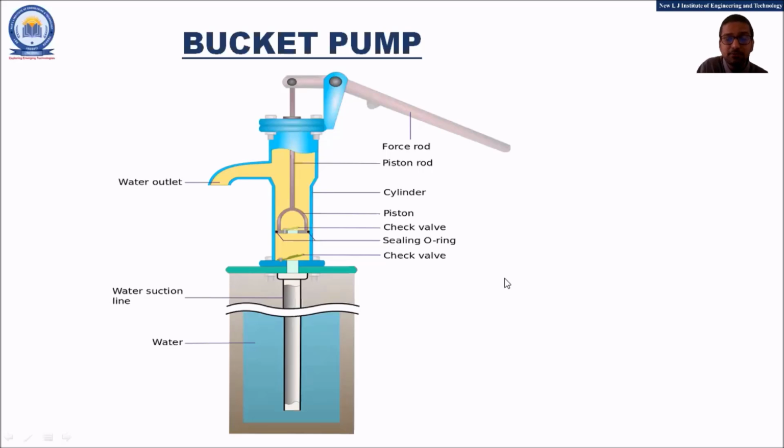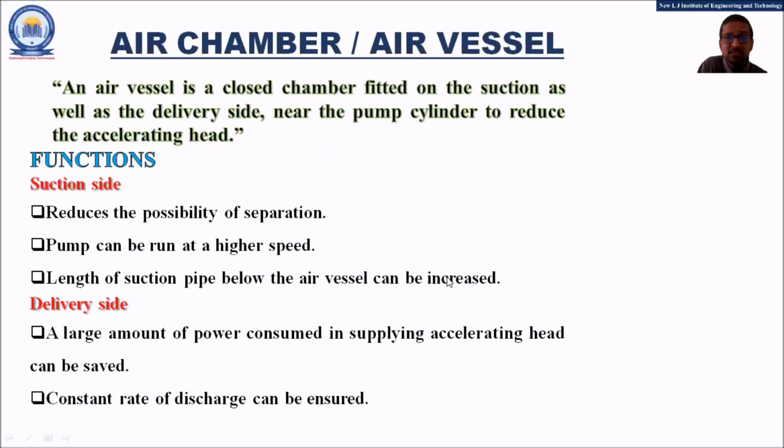Now let us proceed further with the last topic of this session, that is the air chamber or air vessel. The air vessel is a closed chamber fitted on the suction as well as the delivery side near the pump cylinder in order to reduce the accelerating head.